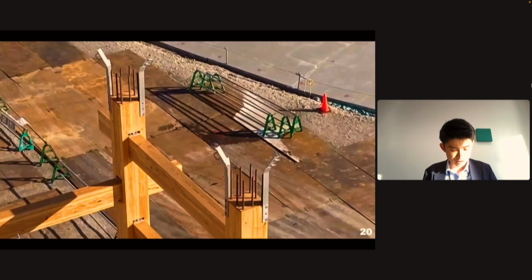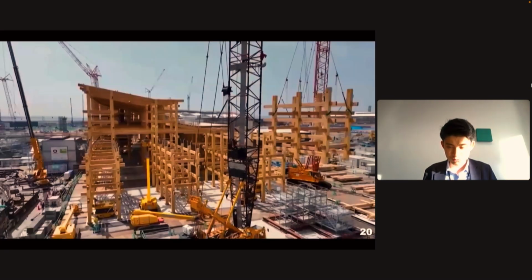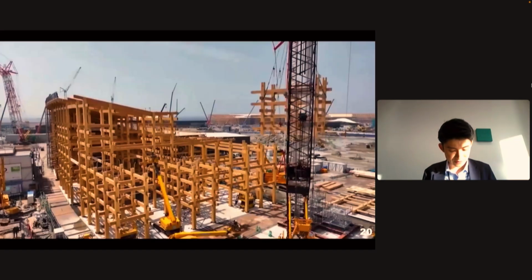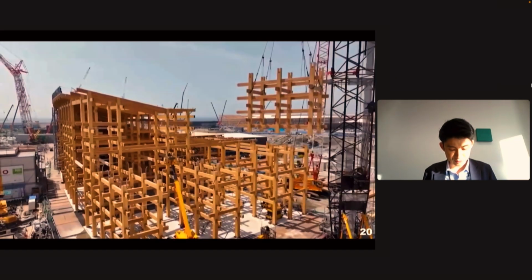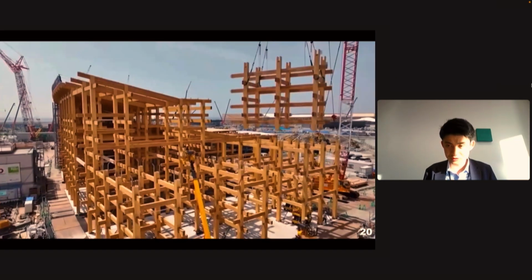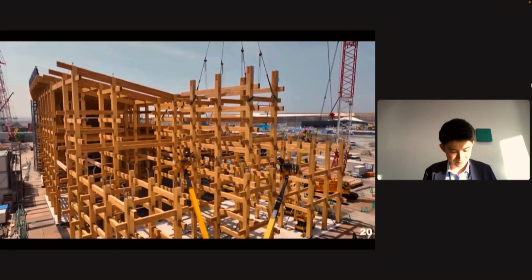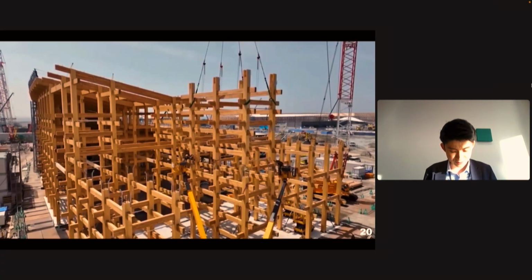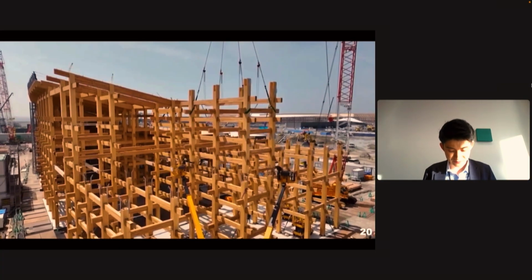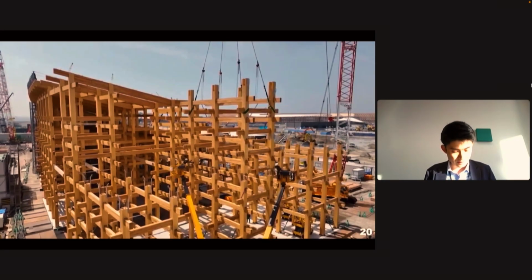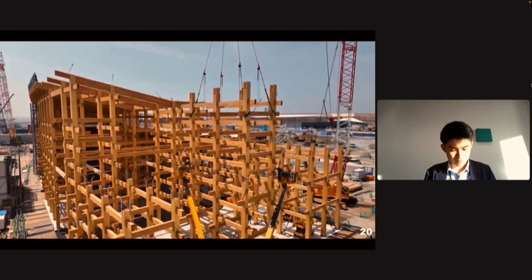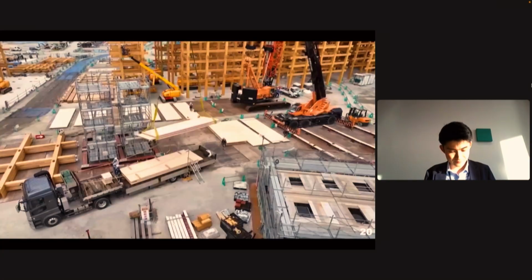To guide multiple crowns accurately in one operation, we developed a guiding jig. Small innovation like this protects both precision and safety. And lifting 6 crowns and 12 beams in a single hoist, we place the 3D unit onto the lower unit.